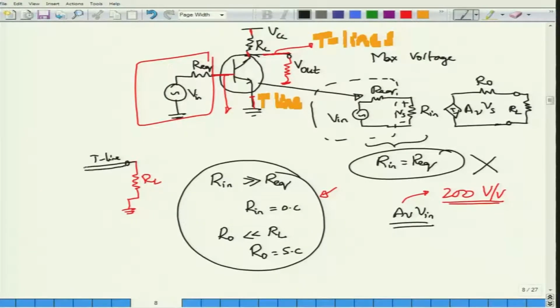Okay. So, what happens here is that the impedance seen looking at this point will not be equal to RL, but it could be some transformation, right. So, some RL that has been transformed because of the transmission line effect. So, it is the same at every point. Whatever impedance you see here will not be the same as the impedance that you expect to see at this point. So, the impedance seen after a transmission line effect is the transformed impedance, and when there is a transformed impedance and you do not control or do not know what the impedances are, then you will essentially end up having reflections at every point.